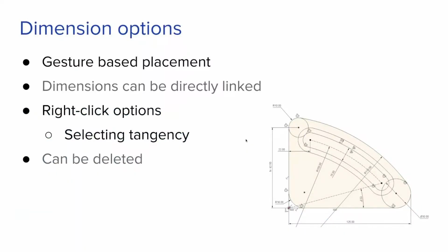Next, let's talk a little bit about dimensions. So dimensions are the next phase of controlling your sketch. So I like to approach things by making sure the geometry is moving right, and then make sure it's sized properly. And of course, there are exceptions, and a lot of people will work with a combination of things. It's not necessarily separate phases. But getting things roughed in and under control will make it much easier to refine the size. Sketching it initially in something close to the right size makes things a lot easier as well.